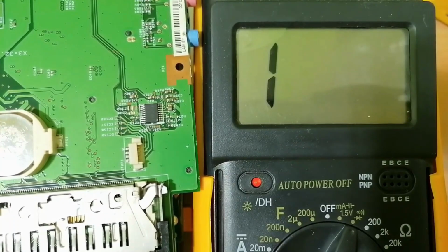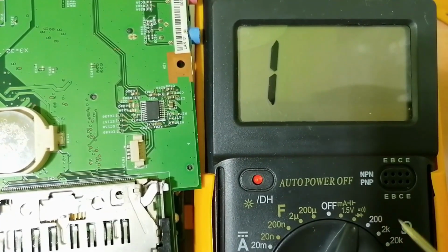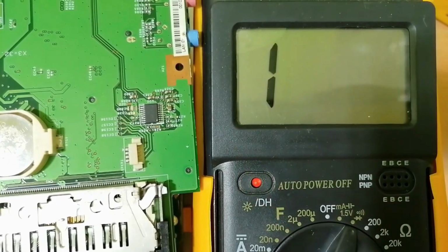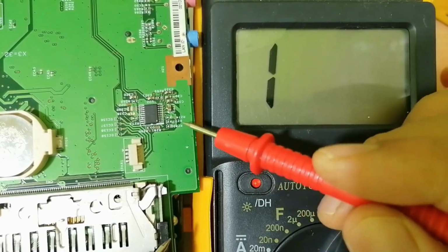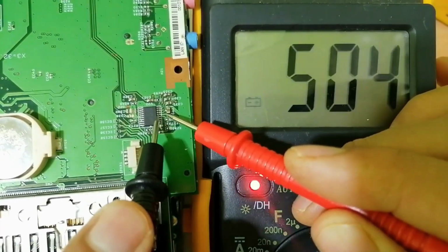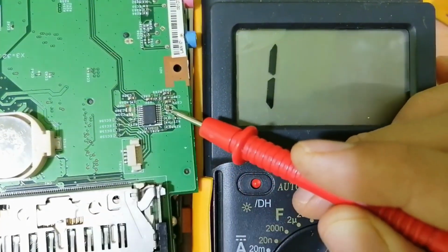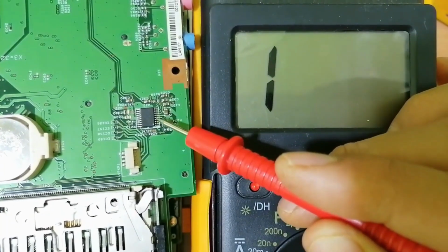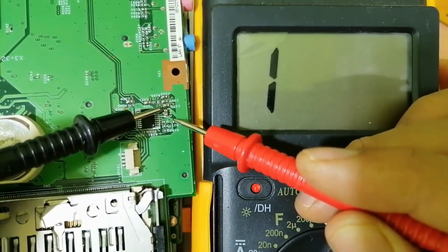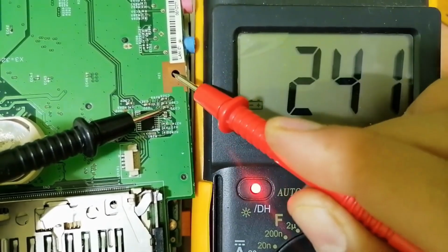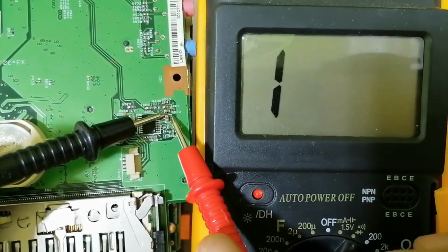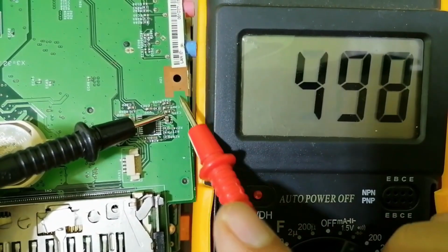So let's put the multimeter to the continuity option. As you can see, let's check. The continuity option is set correctly. So if I put one probe here, and the other probe in this terminal, do you see? So this ceramic capacitor is connected to the IC in this terminal. But in the other terminal, this capacitor is connected to the ground, as you can see. Why? Because we have this path over here connected to ground.